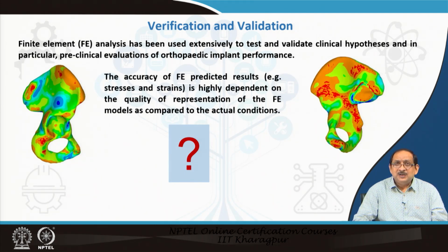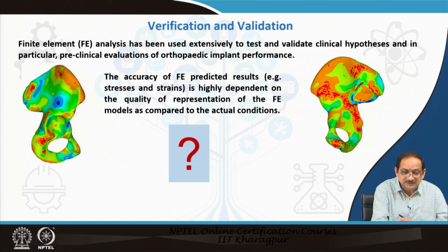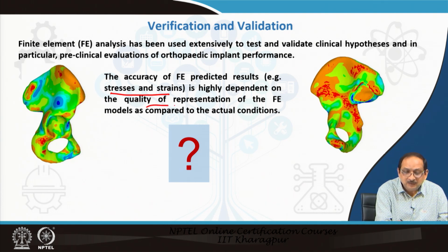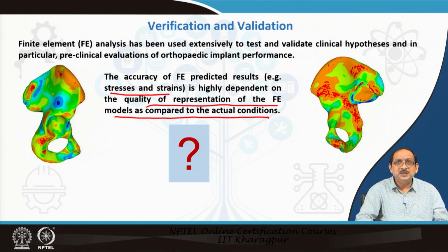The accuracy of the predicted results from these finite element analyses, say for instance when we are predicting stress and strain distribution, is highly dependent on the quality of representation of the FE models as compared to the actual conditions.